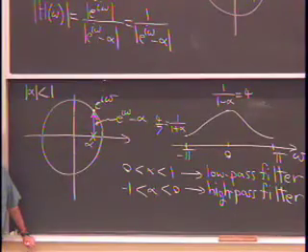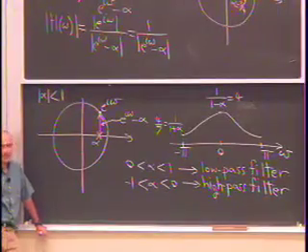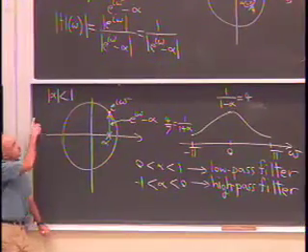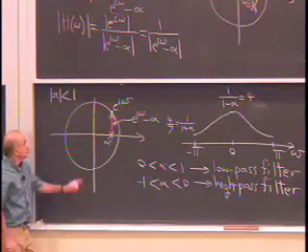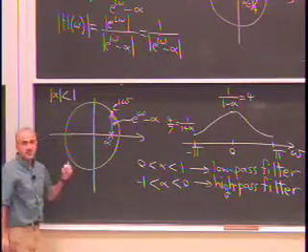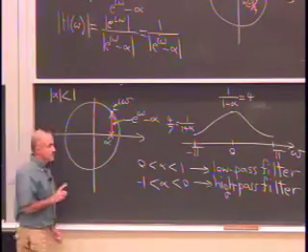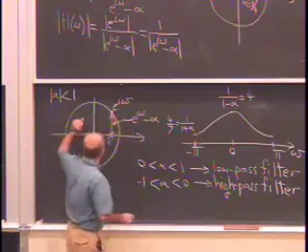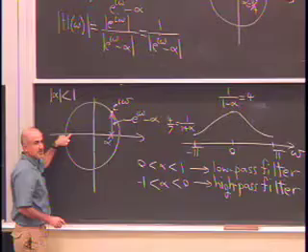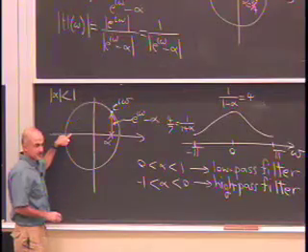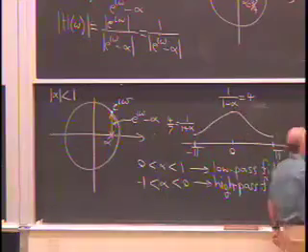So this is all very good. That's exactly the kind of thinking I want you to do. This is what's called design-oriented analysis. So you're given the form of the equation. You only have one parameter alpha to play around with. And by placing that alpha in different locations, you can create different types of filters. Now, one thing to be said about an alpha that's not on the real axis is that it turns your filter into a complex filter, because your impulse response now will be complex valued.